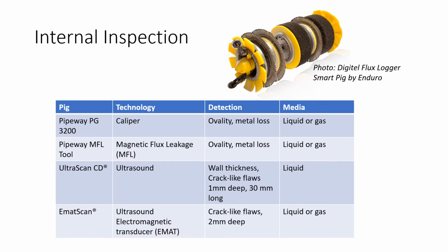Pigging has its challenges and is not always economically viable. Pigs can get stuck in tight bends, or if a pipe wasn't properly cleaned. They also require pig entry and exit stations. Not all pipelines, particularly older ones, are piggable. A friend of mine who is a chemical engineer, who has been disgusted with the troubleshooting associated with smart pigs, once told me, "No pig, no problem."